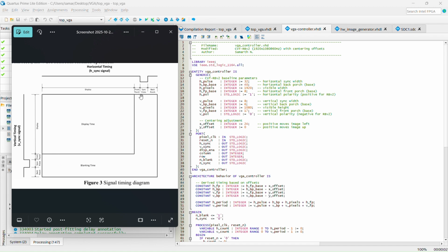So that's what the synchronous pulse does. It basically tells you to move on to the next part. And then the back porch is right after the synchronous pulse, and some time after that you have time to display the next part. So these are the four most important signals, and based on this we generate the image, or that's how VGA starts generating or mapping the signals.